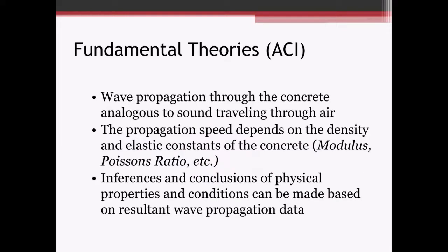So the fundamental theory that ACI 228.2 talks about is the propagation of waves, and it says that it's analogous to sound traveling through air. If you think about it, I'm in a little room here talking to everybody. My voice is bouncing off of the walls, the ceiling, the floor, everything like that. And waves in concrete are going to do the same thing.